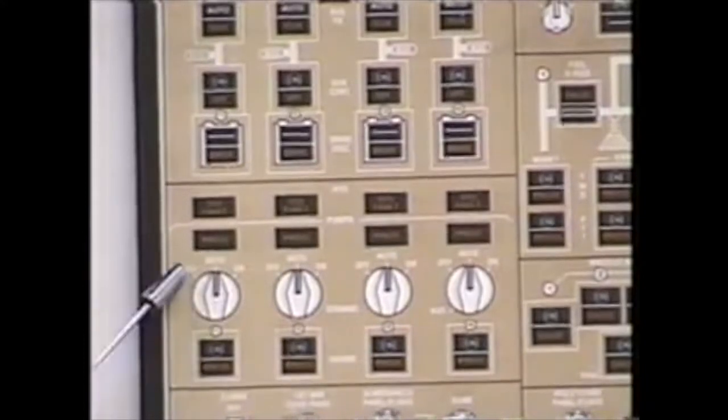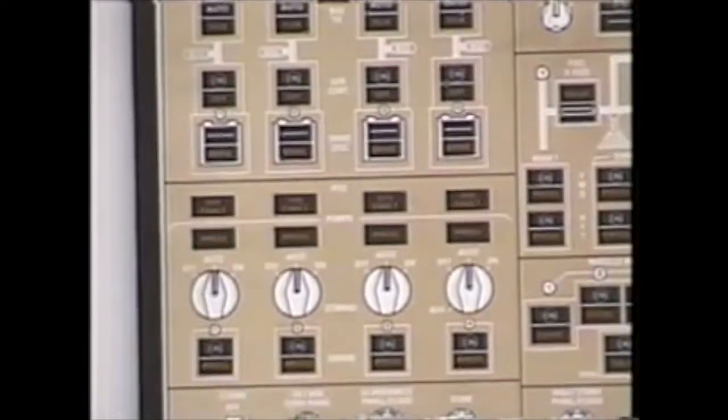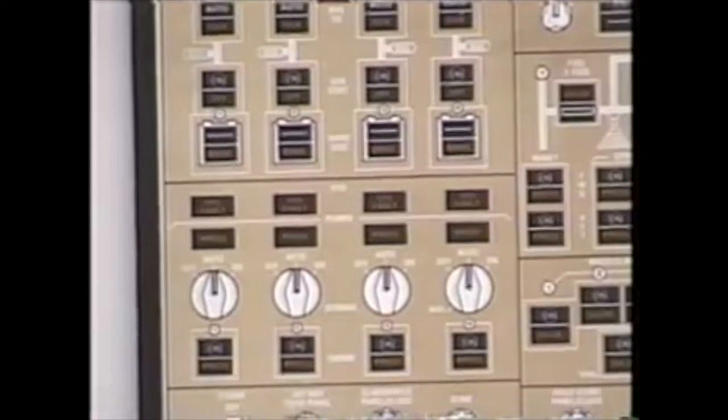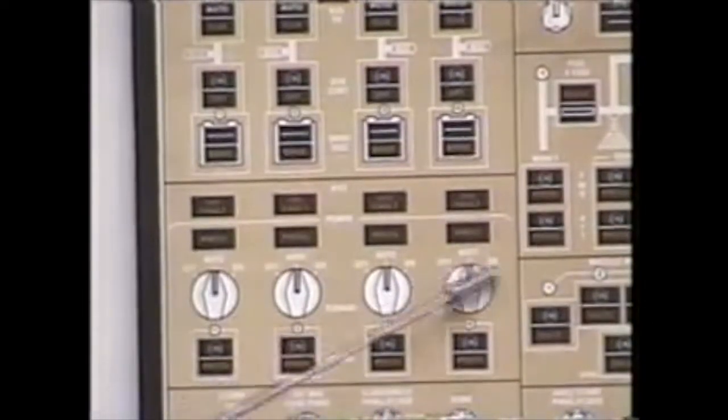With the ADP in the off position, the air demand pump is not allowed to run regardless of what's going on in your hydraulic system. With the ADP in the on position, that air demand pump will run continuously as long as it gets pneumatic air, again, regardless of what's going on in your hydraulic system. With the air demand pump switch in the auto position, there are 2 things which will activate the respective air demand pump. Low system pressure, be it EDP failure or high demand, or taking the respective fuel lever to cutoff, will automatically activate the respective air demand pump.